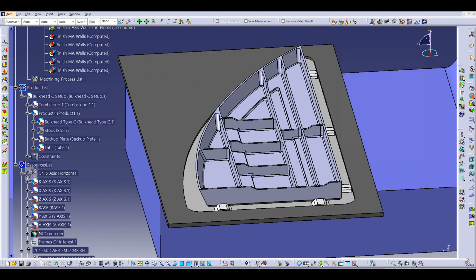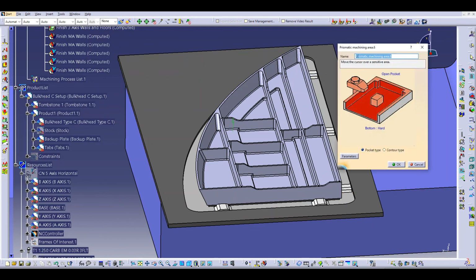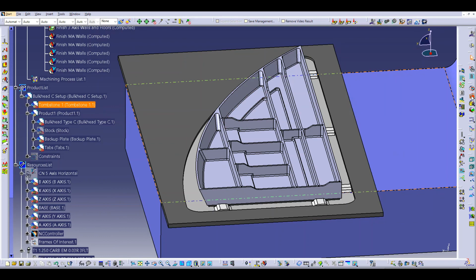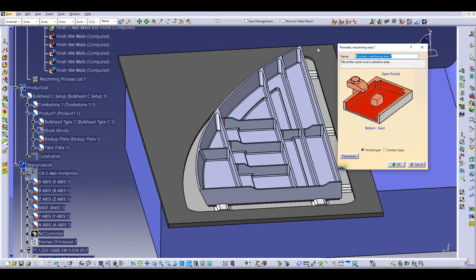Okay, so now I'm going to go ahead and define 2 open floors. It is a pocket, but I'm calling them floors. Open floor 1. Well, let's grab that first. Control C, and we'll call that 1. We're going to leave it on the default open, and we will select that. And you notice the dashed edges here. That's what defines it as an open pocket and means the cutter can go beyond that edge. The other ones are hard boundaries. These are soft boundaries. So that's going to be open floor 1, and then we will do open floor 2.